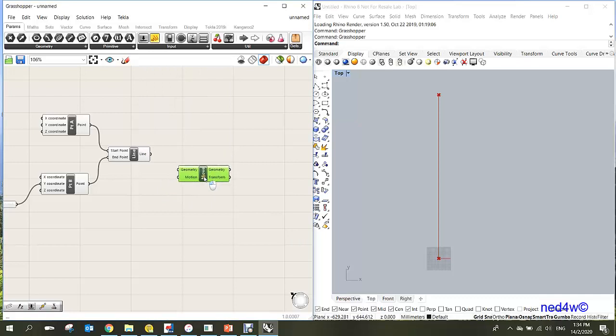So here, the geometry is here. By default, the geometry motion is on 0, 0, and 10, meaning it is 10 millimeters on the ground going to the Z direction. But we need to change that to X. To do that, just simply type here X.